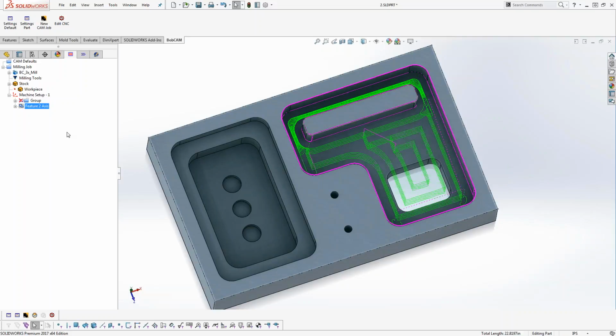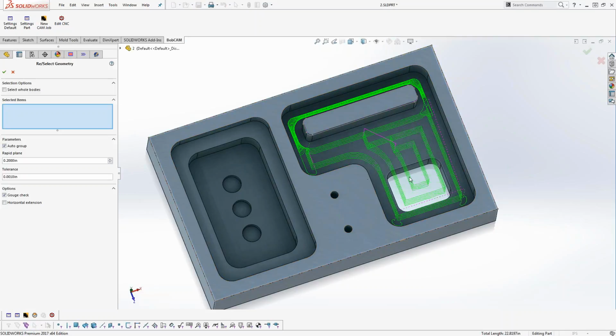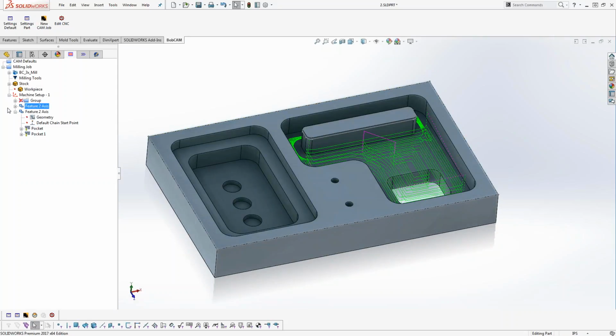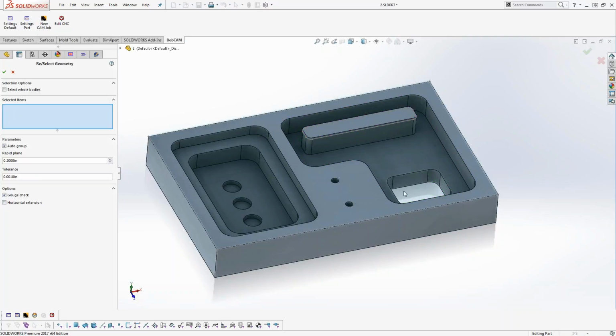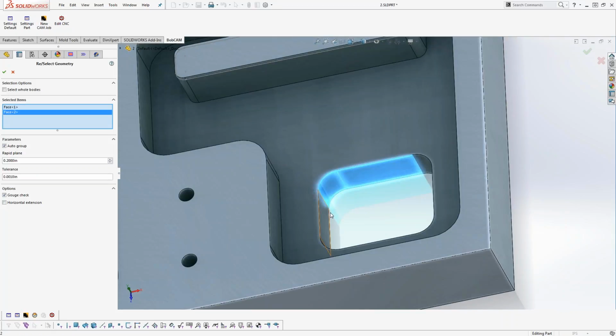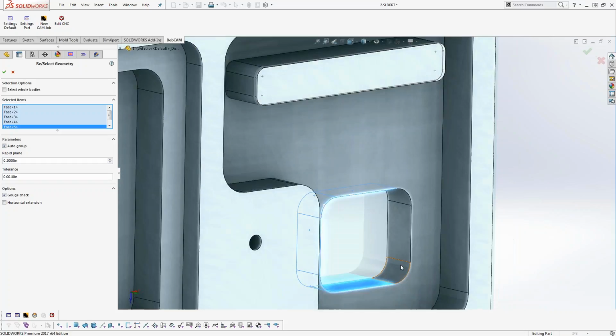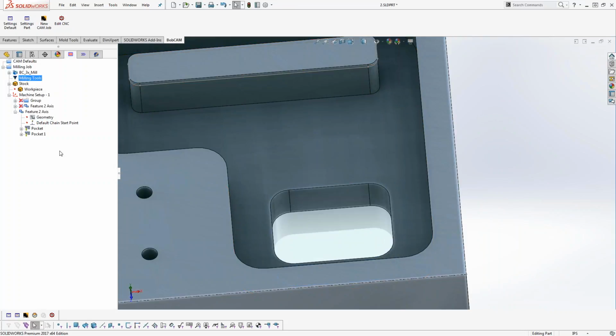If we want to come in here and get into this other pocket, we can say copy. We could say paste. We'll say no. Let me check this down. Let's blank this guy. Okay. So when we come in here and select this, we wouldn't select this top edge here. We wouldn't select these faces in order to do a pocket. If we do that, and we say that's the area we want to pocket, let's select those faces. If we check that down, you can see it actually throws it away. We get no selection if you select the vertical walls.